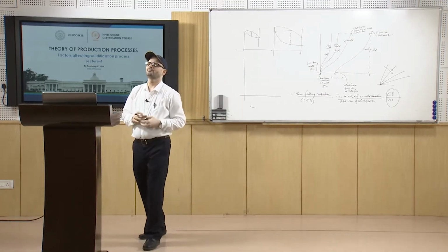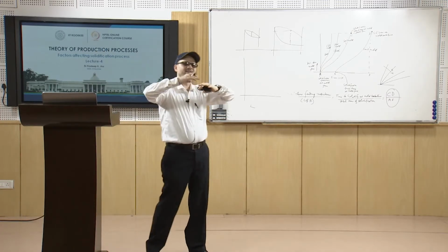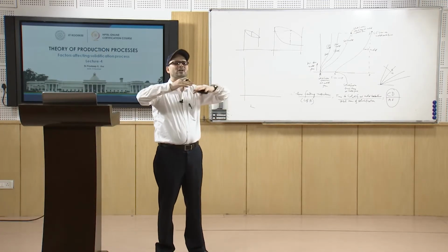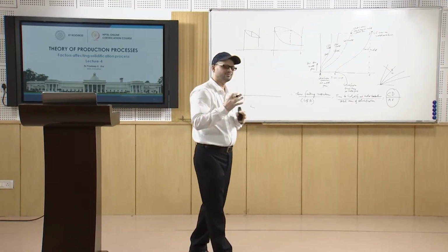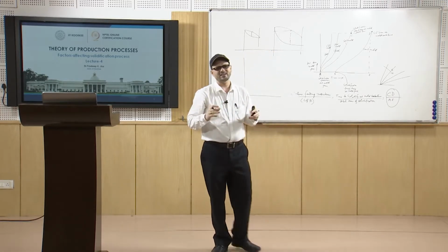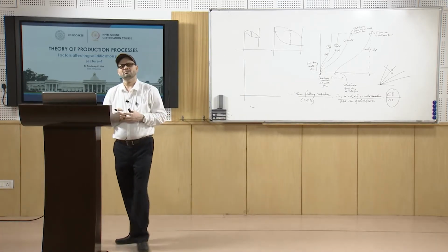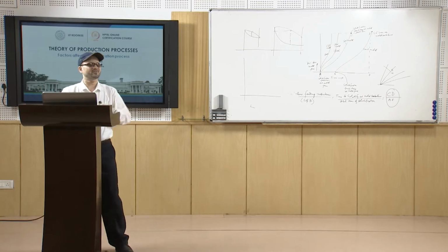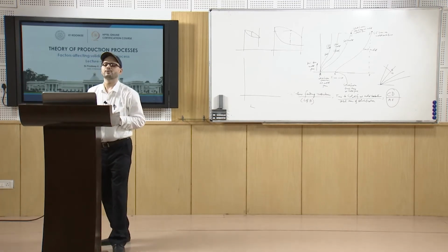If the solidification is occurring at a high temperature, there is more chance of having a large temperature gradient, and if there is a large temperature gradient, there is a chance of larger heat transfer, a steeper temperature gradient line, and in that case there will be a smaller gap. So, a low temperature level of solidification will be increasing the gap. So, it will not be that favorable.